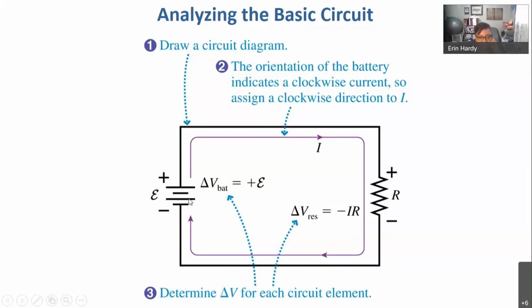If I could flip the battery around, I would still measure exactly the same current in this loop, but then my positive terminal would be down, so it would be like my escalator is moving positive charges down instead, and then it would make sense to flip the direction of that current to counterclockwise. But you should really just look at the battery if you have a single battery circuit with one or more resistors. It gets more complicated when you have more than one battery.